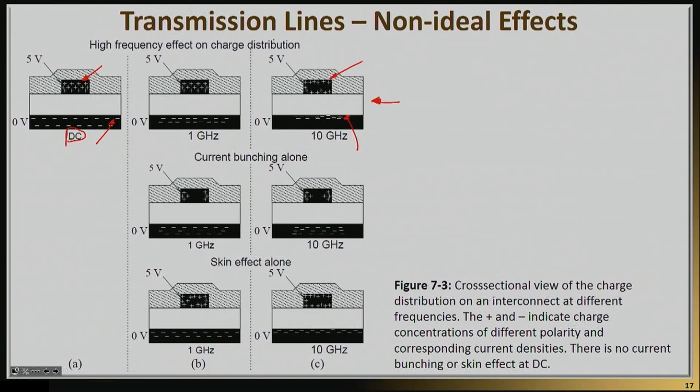So keep that in mind, because a lot of times we forget that, and we basically fail to realize why loss, for example, increases as a function of frequency. And by the way, keep in mind, as I mentioned before, that loss is a cause of dispersion too. So you may have taken the best possible dielectric here, epsilon r, with a loss tangent of maybe 10 to the negative 4, and still find out that the dispersion is not good enough because of the metallic, the ohmic loss.